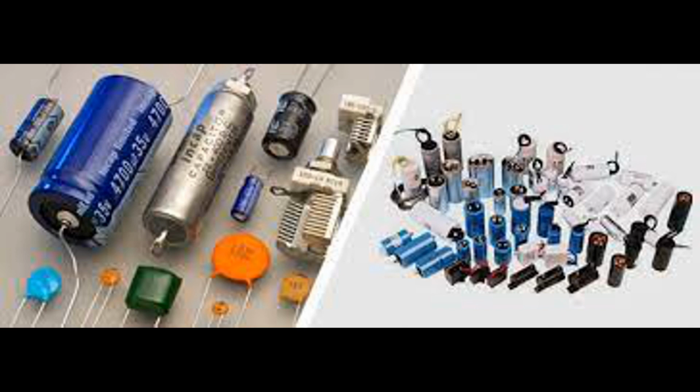Tantalum electrolytic capacitors. Tantalum capacitors generally have lower ESR compared to aluminum capacitors. They offer lower resistance to the flow of alternating current, AC, making them suitable for applications that require low ESR values, such as high-frequency circuits. Low ESR helps maintain better energy efficiency, reduce voltage drops, and improve the performance of circuits operating at high frequencies.